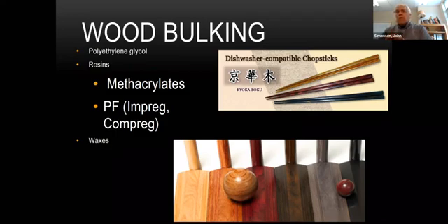One of the things that they'll do is take the tree trunk while it's still green, before it's been dried, and soak it in a solution of polyethylene glycol. It's usually a molecular weight of 1,000 or 800, somewhere in that range, and it's usually about 15% polyethylene glycol. Everybody calls it PEG, P-E-G. So you soak the wood in PEG, and the polyethylene glycol will actually displace the water. And it's a matter of simple statistics.